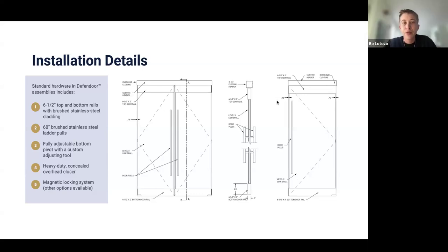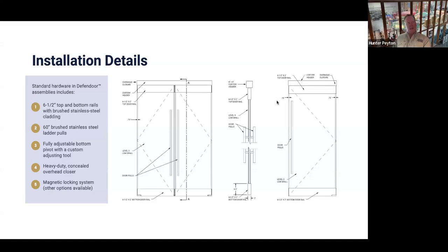Awesome. Does the electronic locking system have a fail-safe or fail-secure option, and how does it integrate with fire alarm systems? Again, I'm not a low voltage guy, so I hate to just not answer, but I don't know how that is. Right now, the doors you saw are using a mag lock, so it does not fail safe unless there's a backup battery. We are working on a new locking system that you can set to fail open or fail secure, and it doesn't matter if the power is on or not.